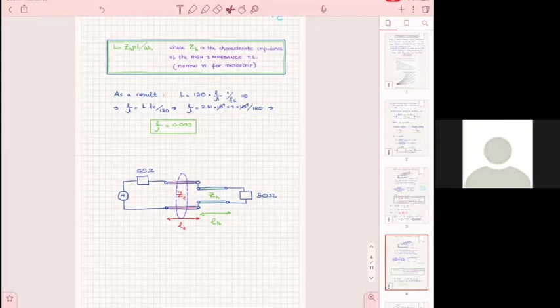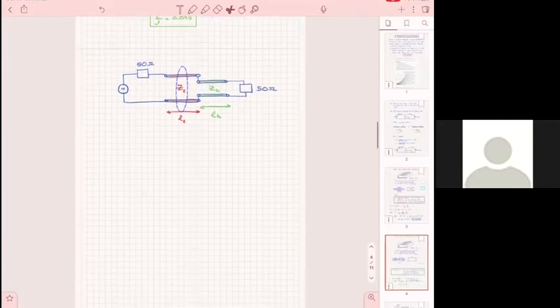It just happened here. The values of L and C and the values of low Z or high Z just happened to come out like this, but it's not necessarily true that it's going to happen all the time. You just need them to be very small. So you need to have a zero in front. You need to have a 0.0 something. You need them to be at least smaller than a tenth of a wavelength, to say that they are small. That's what you need. Okay. Thank you. Sure. Any other questions about that?